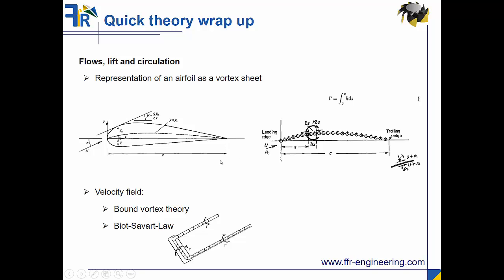And you have some more ingredients like the Biot-Savart law, which we'll see in a second, and also the bound vortex theory, which basically states that you have closed loops of these vortices, which you see here. So it cannot be that they just end like that, at a dead end. Either they connect within your flow, which you observe, or if that's not the case, they have to leave your flow, and then they act like an outward boundary condition.